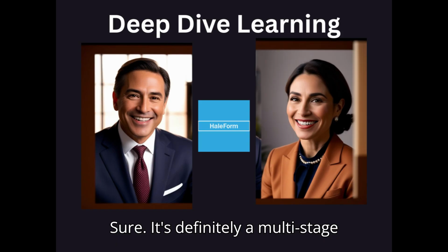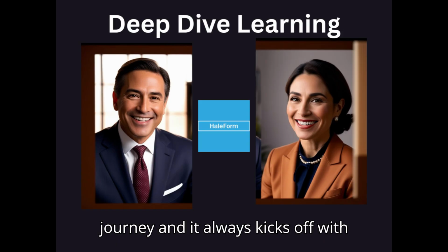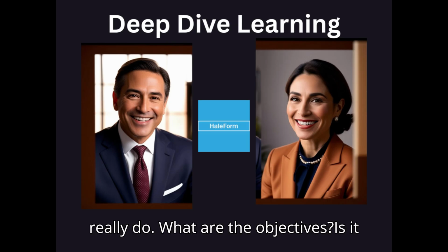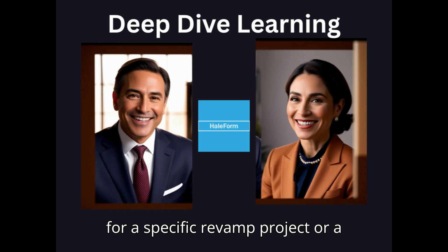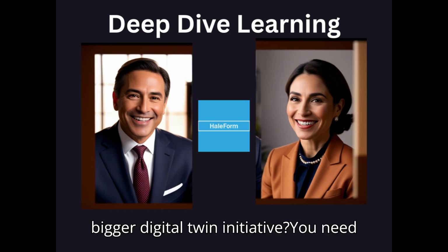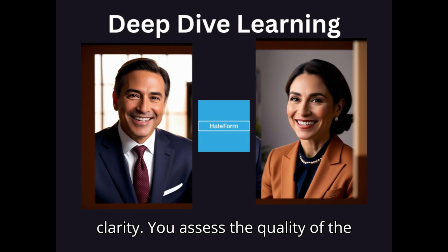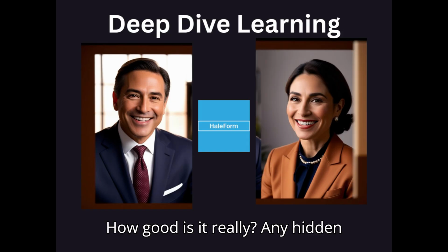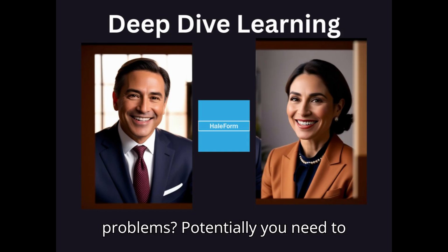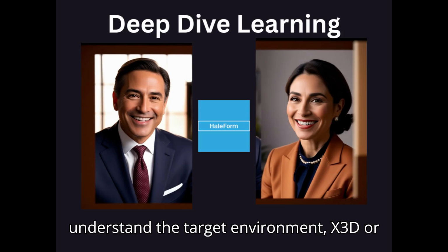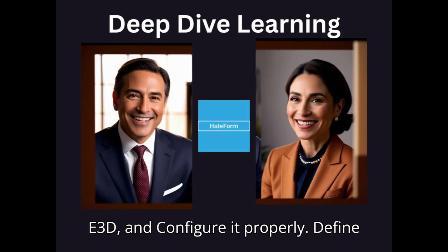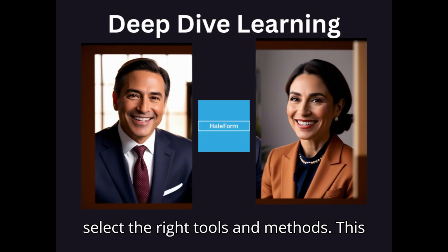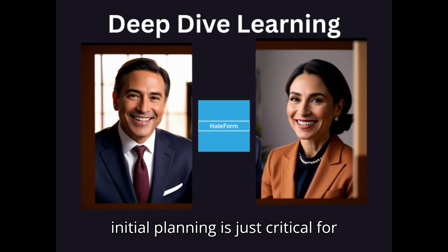Sure. It's definitely a multi-stage journey, and it always kicks off with thorough assessment and planning, always. Got to know what you're getting into. You really do. What are the objectives? Is it for a specific revamp project or a bigger digital twin initiative? You need clarity. You assess the quality of the source data, the PDS or PDMS models. How good is it, really? Any hidden problems? Potentially. You need to understand the target environment, X3D or E3D, and configure it properly, define the scope clearly, what exactly is moving, which parts of the plant, and select the right tools and methods. This initial planning is just critical for success.